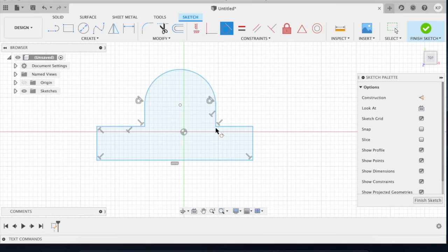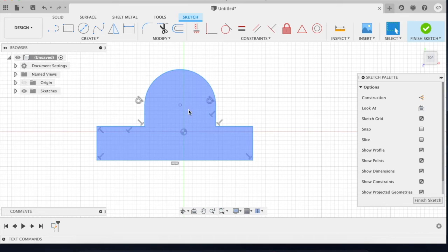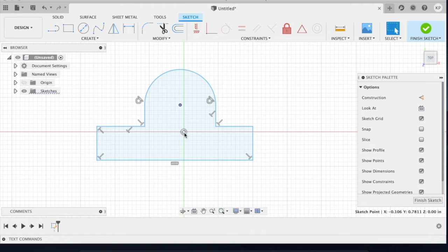that line becomes tangent. The next thing that we want to do is we need an anchor point. That's why we start at this origin. It gives us an anchor point for our dimensions. So we're going to move that. I'm going to hit escape to get rid of my tangent tool, or you can hit the select button. I'm going to use my shift key again, and I'm going to select that center point, and then I'm also going to select my origin, my center.